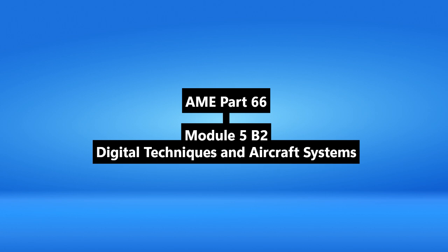Vital for IMA. The module also mentioned the DO-178 evolving from B to C with supplements. Why the updates? Technology marches on. DO-178C from 2011, and its supplements were needed to address newer software development techniques that weren't common when DO-178B was written. Things like model-based development and verification, that's DO-331, using object-oriented programming languages, DO-332, formal methods which use mathematical proofs, DO-333, and also qualifying the software tools used in development, DO-330. If you're relying on a tool to automatically generate code or run tests, you need to prove the tool itself is reliable. Makes sense. Tools can have bugs, too.